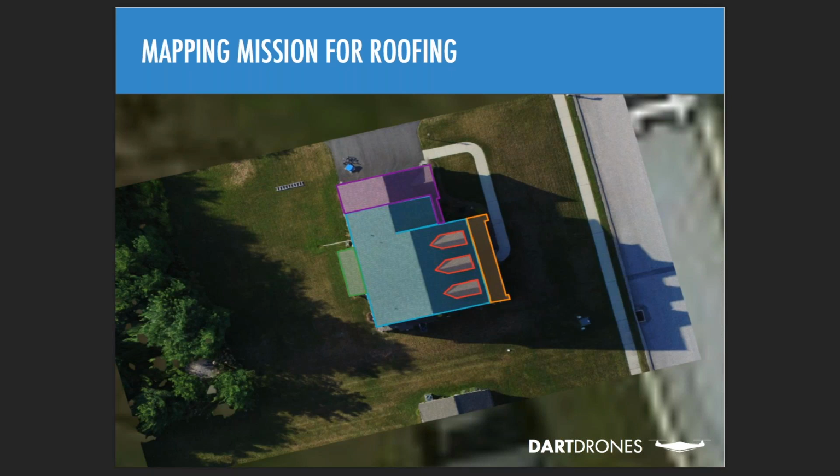So they were looking for some help as far as estimating area and things like that, and I told them, well, hey, let's put up the unmanned aircraft and fly around, see what we can do, and use the DroneDeploy software, and planned out the flight. Was able to capture the images very quickly, put it together, and you can see here, using the different tools in the software, we were able to select the different areas for the different elevations, the different parts and sections of the roof, and get the area calculations for those materials.